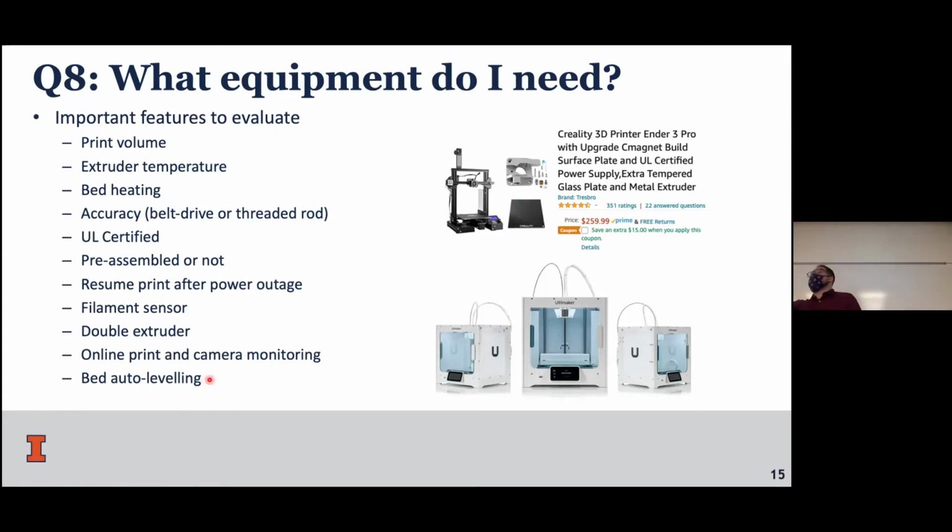If we look at the printer on the left, there's a mechanical dial on it that I installed. This is to make sure that the bed is fully leveled with the extruder. If you don't have perfect leveling, and perfect is 50 microns difference, what's going to happen is your part is not going to stick well to the surface. It might unstick, and then you end up with a big blob of filament, something you do not necessarily want. So if you want to buy a printer, that's what I would recommend checking first, to avoid any problems and make sure that your printer is fitting your needs.